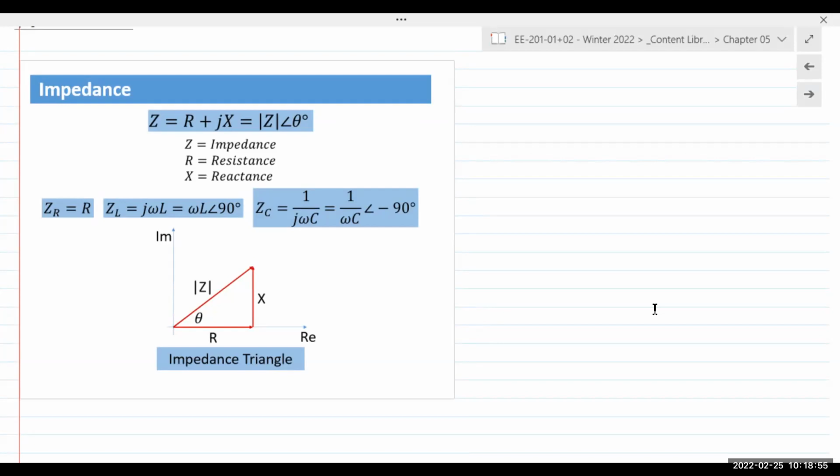For a capacitor, when it doesn't change, it behaves like an open circuit. There is no current flowing through the circuit. But the moment it starts to change, current flows in the circuit. So the faster it changes, the lower the opposition in that capacitor. In terms of frequency, inductor reactance, noted by XL, is given as 2 pi FL.